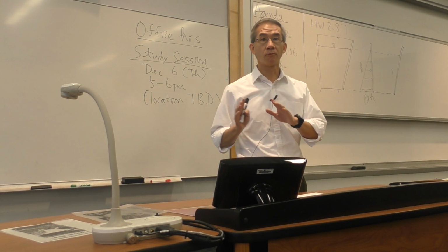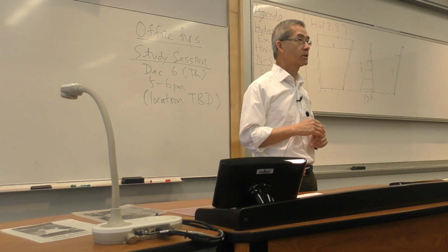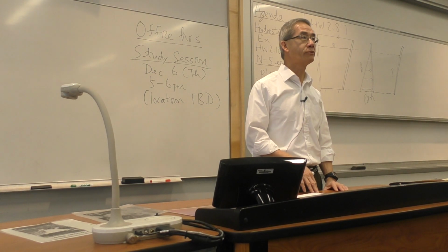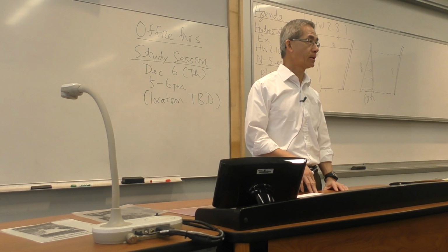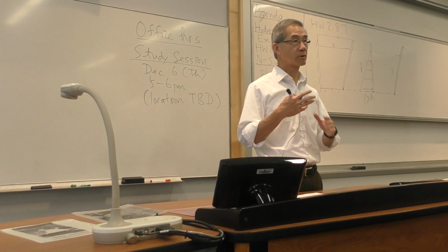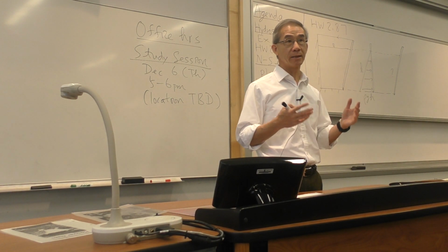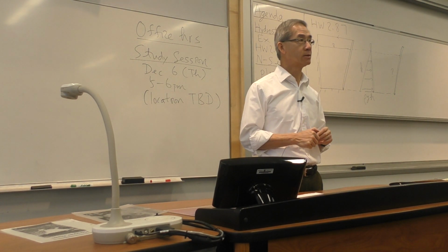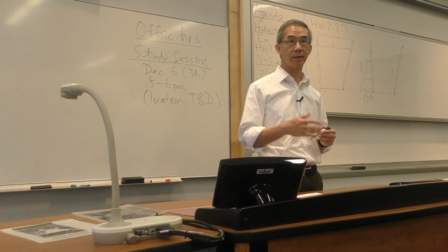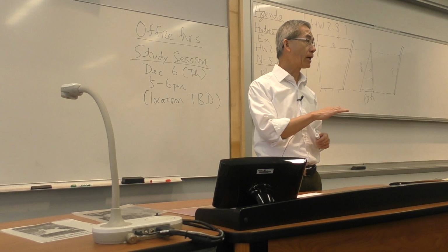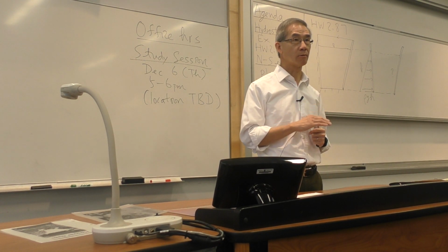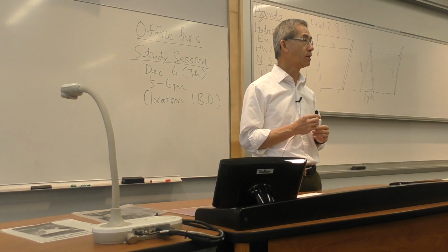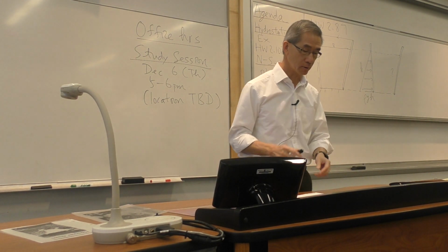So any question on what we covered last time on hydrostatics? Do you understand the concept of what I call a pressure prism? Can you comfortably calculate the average pressure based on that, and then the force, which is pressure times area, and then the moment arm, which requires you to know the center of pressure, or the location of the resultant force? All of these are just statics. Any question? No? Very good, okay.